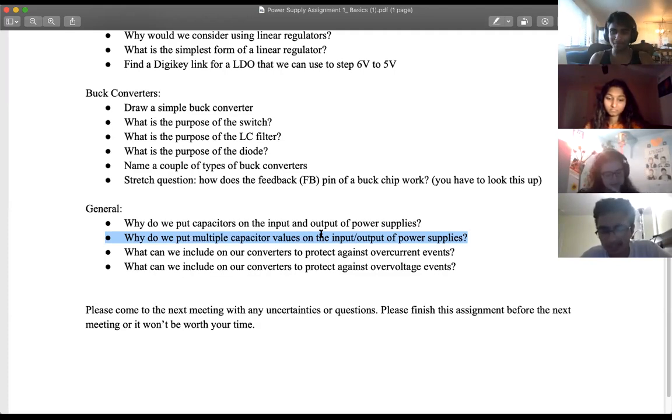That tells you where the filter dips. Bigger capacitance means you want it for lower frequencies. So you want the smaller capacitance values for higher frequencies, closer to your chips or your supplies. If you read the Eagle document, they talked about that briefly.